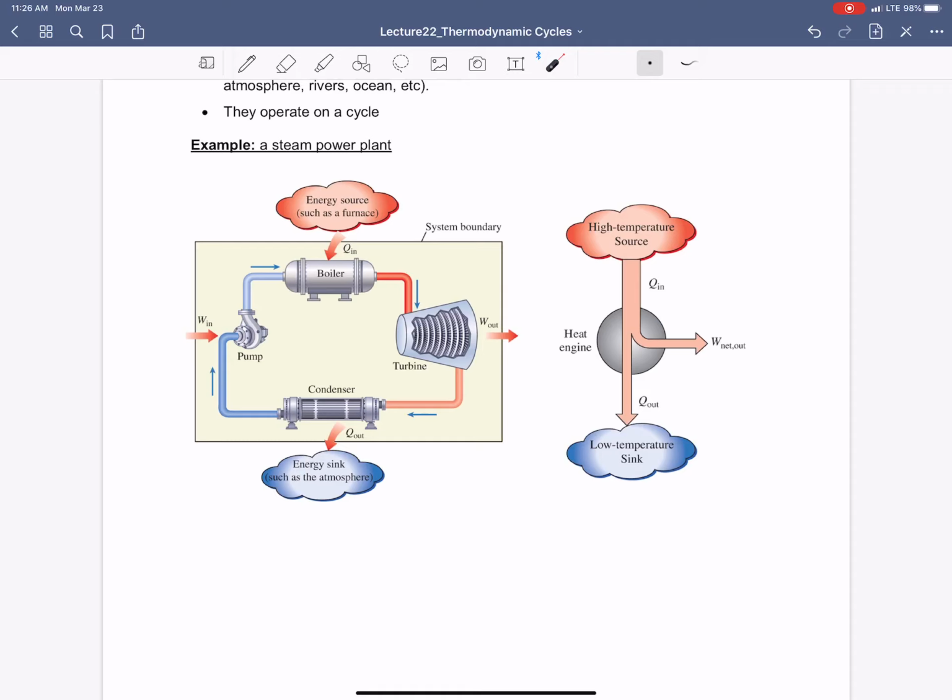Now this high temperature, high pressure steam goes to the turbine and runs a shaft by rotating a rotor inside, and as a result, the turbine generates power. Then the steam, after using its energy in the turbine, goes to a condenser where the remaining heat is rejected by cooling the steam down to water. Then this water goes back to the pump to make a cycle.